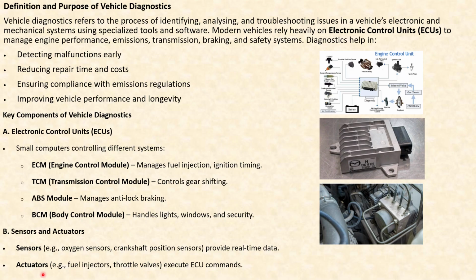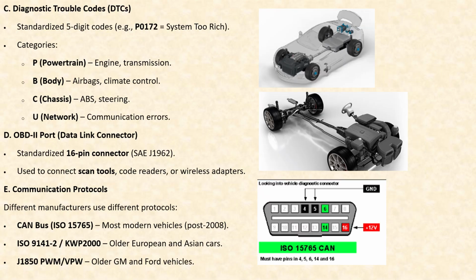Actuators, in very crude terms, are the actual executives. They are the actual executioners. For example, fuel injectors or throttle valves execute the ECU commands. Based on the commands, whether they inject the fuel or enhance the fuel injection, all these things are taken care of by the actuators.